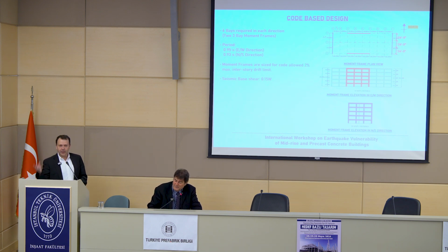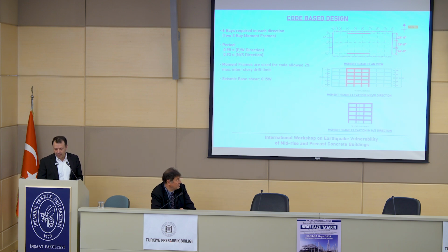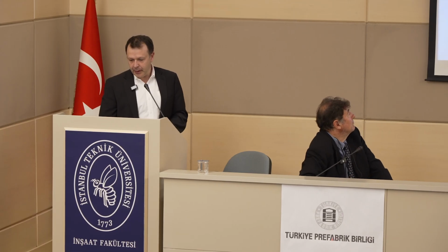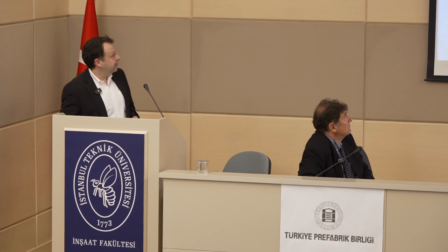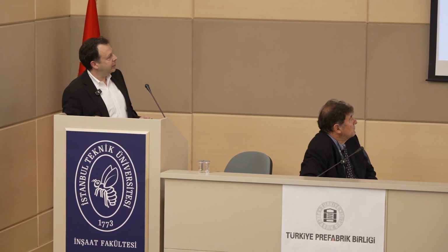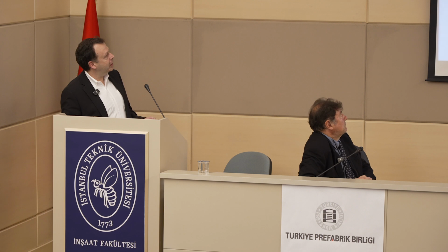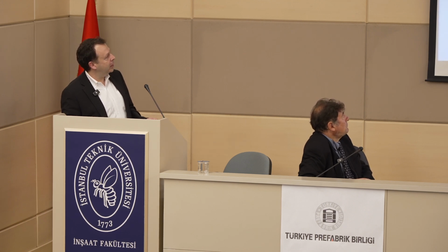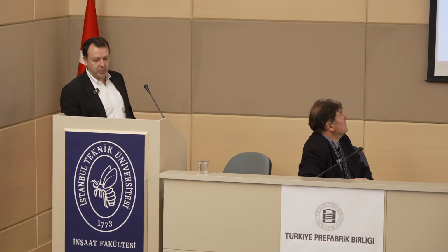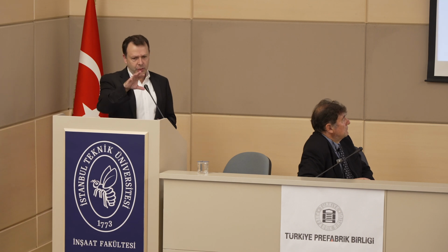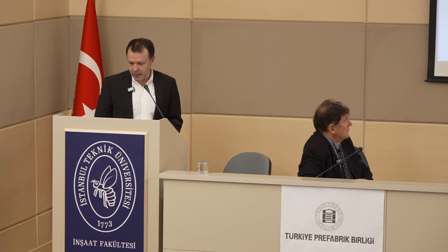And so with that, our seismic base shear would be around 0.15 there. We can get back to this, but in terms of reinforcing, just I think what's typical, we do go with a reinforcement through the beam column joints, the reinforcement in the columns, and this is just a typical reinforcing, and then usually at the ends of the beams, tighter spacing, and you should have all the details printed out for you as well.